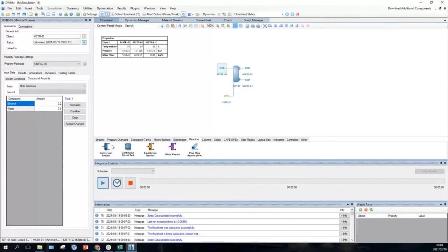And so you choose a conversion that is reasonable based on the literature, and then in your reactor design, you will usually model that in another language rather than doing it in DWSim. So you'll know that your aim is to get 70% conversion, and then you will use your Python or whatever your preferred tool is for designing the reactor itself. So this is the one that you're going to use, and CSTR is nice to use every now and then.